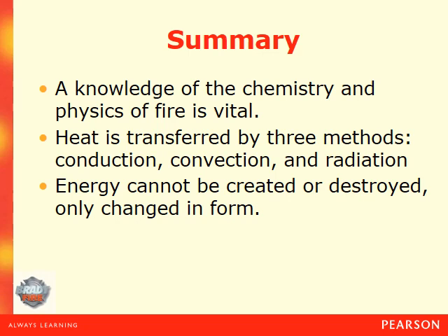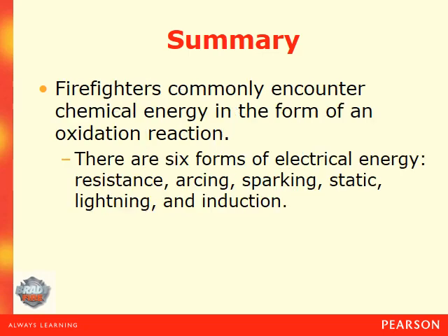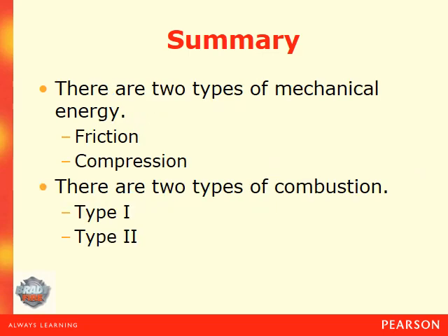Heat is transferred by 3 methods: conduction, convection, and radiation. Energy cannot be created or destroyed. It can only change form. Firefighters commonly encounter chemical energy in the form of an oxidation reaction. There are 6 forms of electrical energy: resistance, arcing, sparking, static, lightning, and induction. There are 2 types of mechanical energy: compression and friction.